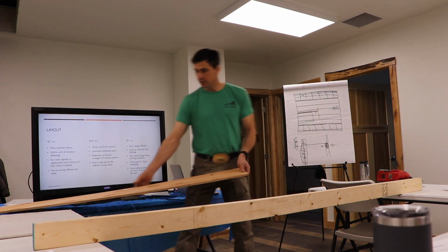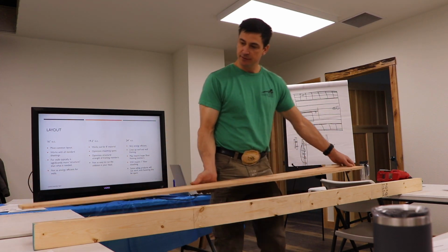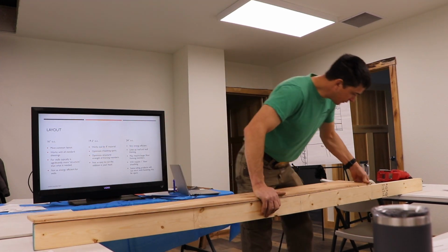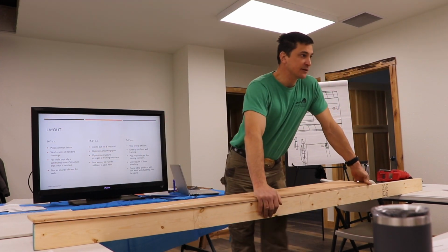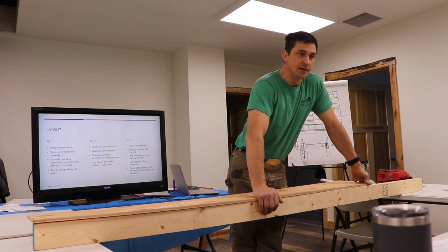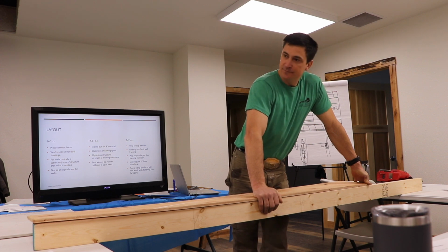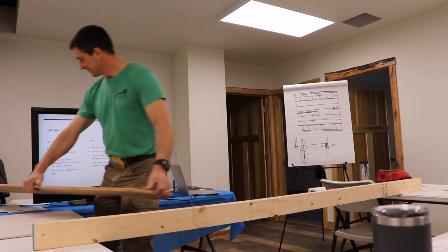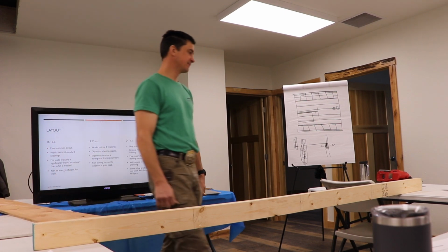And then we go and we put our sheathing on, and we run that flush to the end. And what do you know? Did it hit the middle of our truss? Nope, it's on the side. Dirty dog. Guess I gotta do some blocking. Okay? So what went wrong?